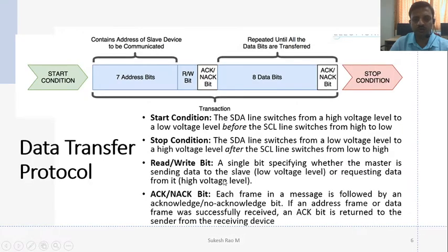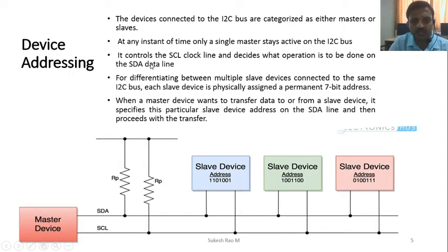It is as good as calling your name by a register number. I need a unique identification. So after generating the start condition, they put the address serially: 69H will travel here because I want to communicate with this slave device.